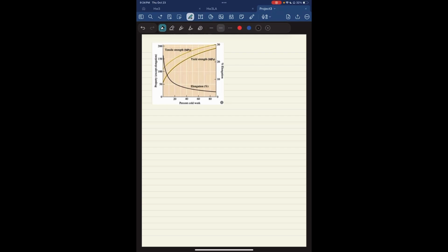In order to get a final diameter of 3 and a final percent cold work of 12%, we can treat it as if we had elongated it to a certain point and then annealed it to reset the percent cold work, and then we elongated the final 12% to get the values needed. So in order to do that, we can set it up as 1 minus 3 over x squared equals the 0.15, which is the 15% left.